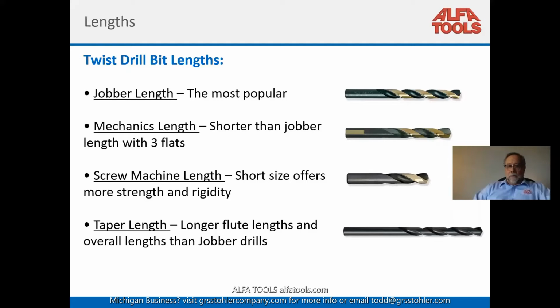Taper length. This is a term that was derived from taper shank drills, which we'll see on another slide, but it still is a straight shank drill. There's nothing taper about it. It's just longer than a jobber. The taper length throws a lot of people off when you talk about that as a description, but really what it is, it's a longer series of drill.